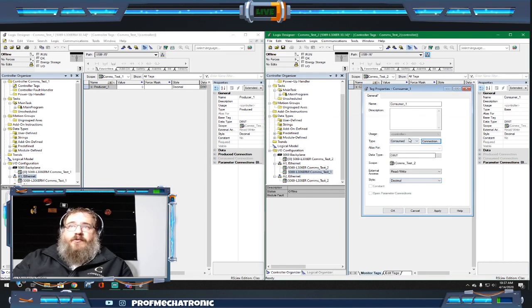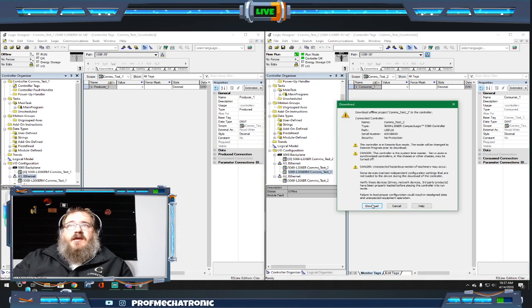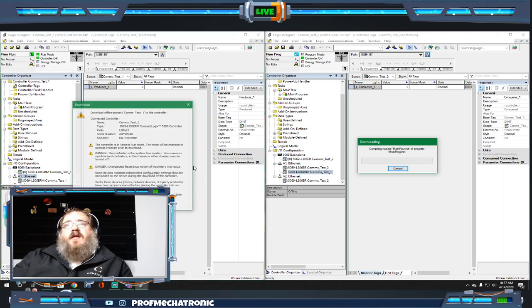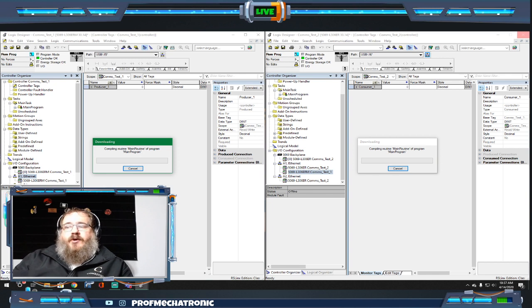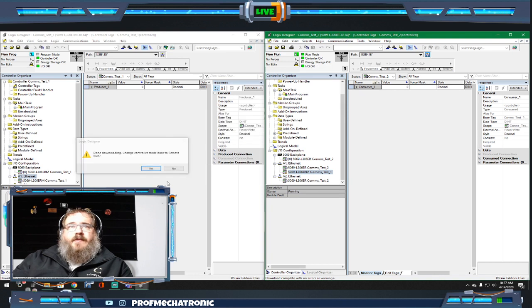Now that we've got this all set up, we know it's consumed, we've got the DINT, we've got everything set up here. We're going to hit apply and OK. And now for both of these PLCs, we are going to download that new information that we did offline into each of those PLCs. Now doing this, we want to make sure that we have all the information required for both so that they can both be downloaded and set up. And we'll put both of the controllers back into run mode as they come up.